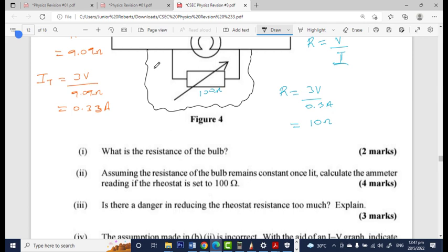Somebody say 0? Yes, sir. Someone did 0. So I was suggesting that somebody should say 0. A piece of wire will have a resistance of 0 ohms, yes? Now, once we connect a 0 ohm wire across this right here, which is due to the rheostat being at 0, so instead of the rheostat being right here, we just put a piece of wire. Cool?